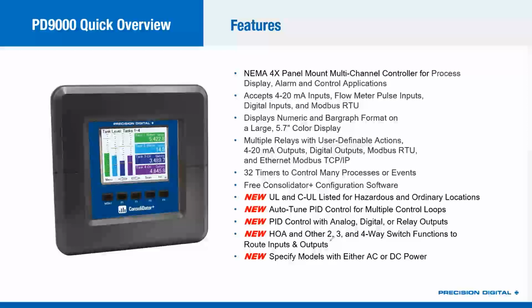We've also added all sorts of 2, 3, and 4-way switches, including HOA switches, and we'll cover what hand-off-auto, or HOA, switches are in a bit, but very common in pump control applications. And we now specify models to either be AC or DC powered. This is the one sort of negative of the UL listing: the UL did want us to break out those power supplies. So whereas in the past your Consolidators would have both high voltage and low voltage power options, now you have to specify if you want it to be high or low voltage.